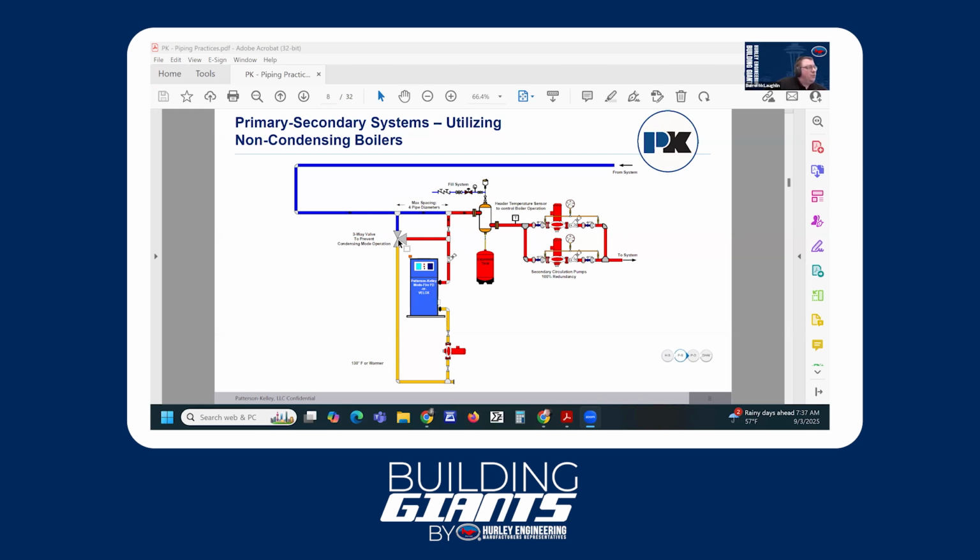Now here, this is a straightforward way. If you look at this three-way valve, we're not showing how it's controlled on this drawing. It could be thermostatically controlled. We could have sensing bulbs and actuators, and there's many ways you can control this three-way valve. But the basic point is we have a three-way valve to protect this return water temperature. And you can see 130 degrees is what we're trying to stay above here.